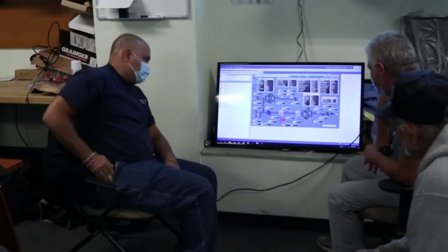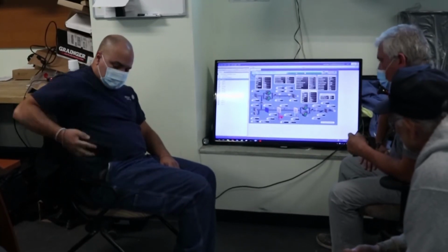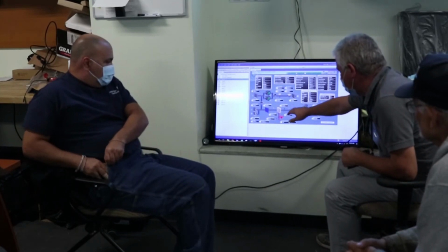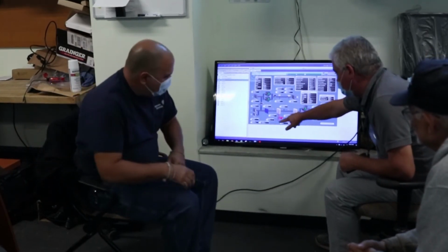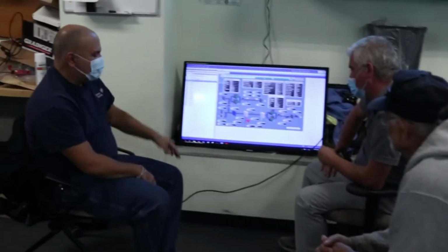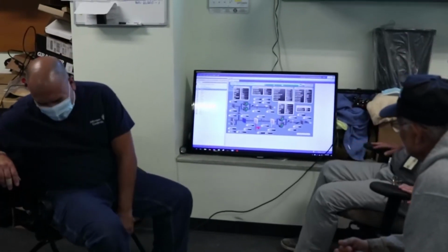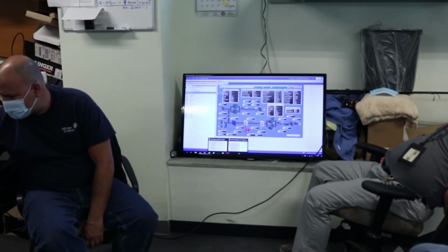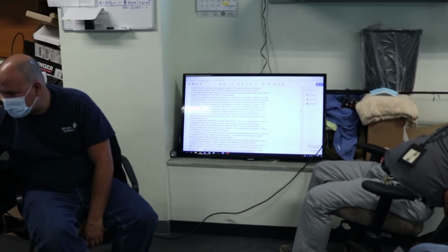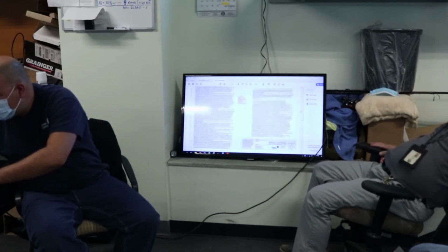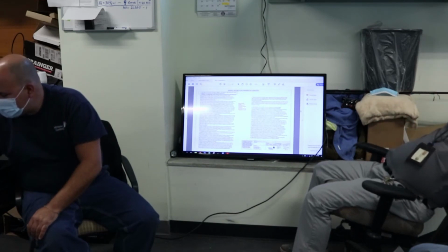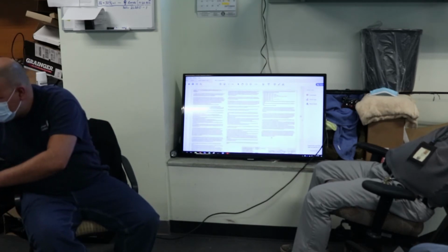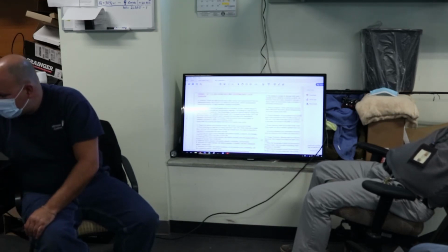The circulation pump, when is it started? When the low temperature alarm is activated, it should be started. There's a sequence for the preheat. I believe it's based on outside air temperature, because on the Honeywell, when the unit went to alarm with freeze protection, this pump is started.